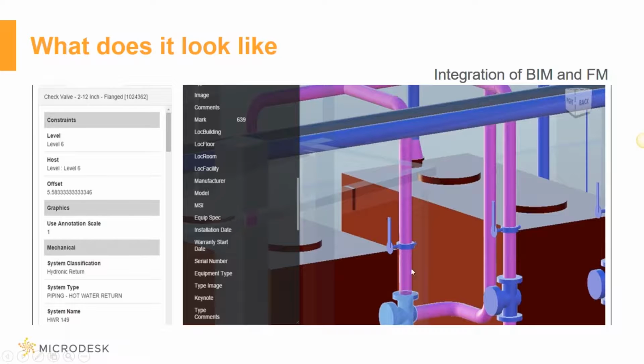One is the placement of the valve. Where physically is that valve? So that's number one. Second is, what is this pipe that's connecting to the valve, and what's this pipe that's leaving the valve? In many cases, when you have a valve and there are two different types of material, one entering and one exiting, those are points of failure for operations. And what you want to try and do is minimize the number of round trips that operations needs to make to the site where they have to do a repair.